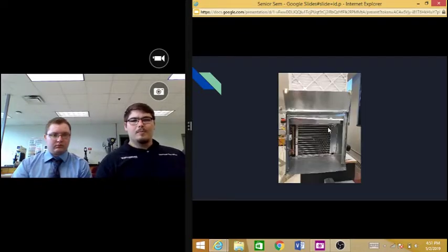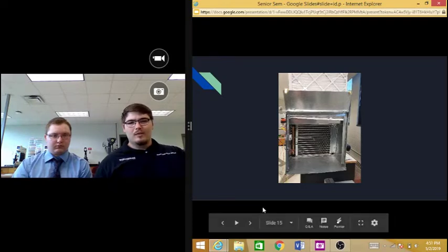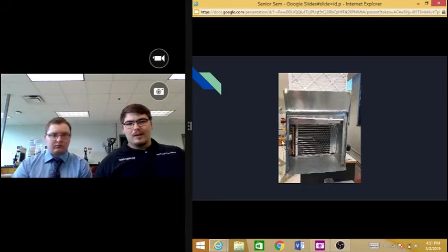This is a close-up image of some of the actual unit again. We created a door here where we could open up to replace the filter. You can see here's a DHT sensor. It's very difficult to see, but there is actually a pitot tube coming up through here. It's kind of blended in with the heat exchanger. There's a condensation pan here in the bottom. And there's two barometric sensors here where they're wired off to the side.